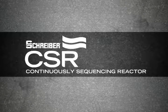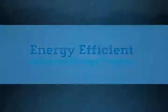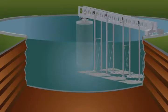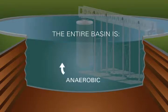Schreiber's continuously sequencing reactor is an energy-efficient activated sludge process that performs all of the process phases required to achieve biological nutrient removal in a single basin. The fundamental concept behind the CSR is to periodically change the environmental conditions in the basin to produce the three process phases, oxic, anoxic, and anaerobic, in sequence over and over in the same basin.